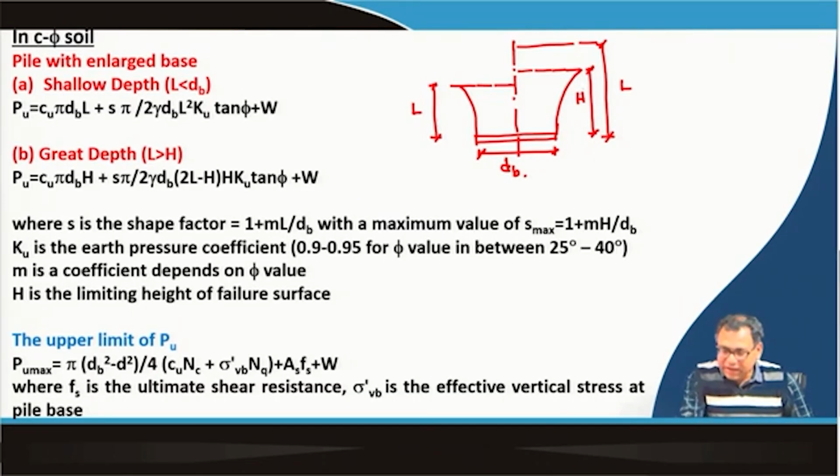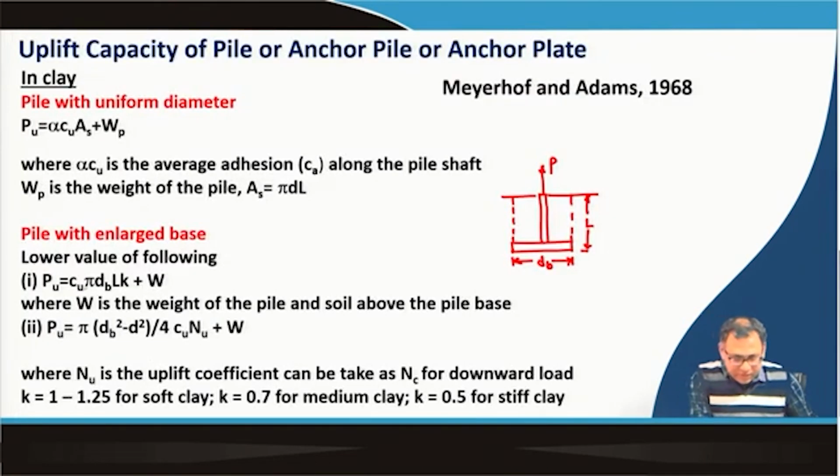So, h is the height up to which the failure plane has extended under uplift. Previously also this was under uplift. Then it is assumed that there will be a block which is moving up, and here also this is assumed. That is why the adhesion factor alpha is taken as 1, because in such a case the adhesion is between soil and soil.